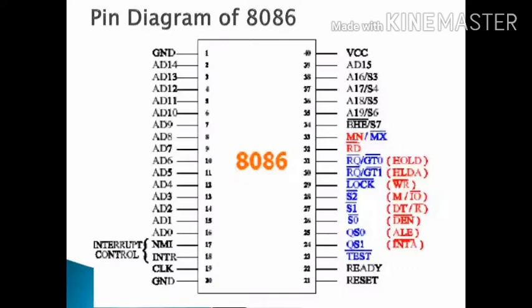So these 4 bits of address are 0000 during the first machine cycle, because 8086 is sending out the address for accessing input output ports, and in the later clock cycles these pins will send out S3 to S6 status information.